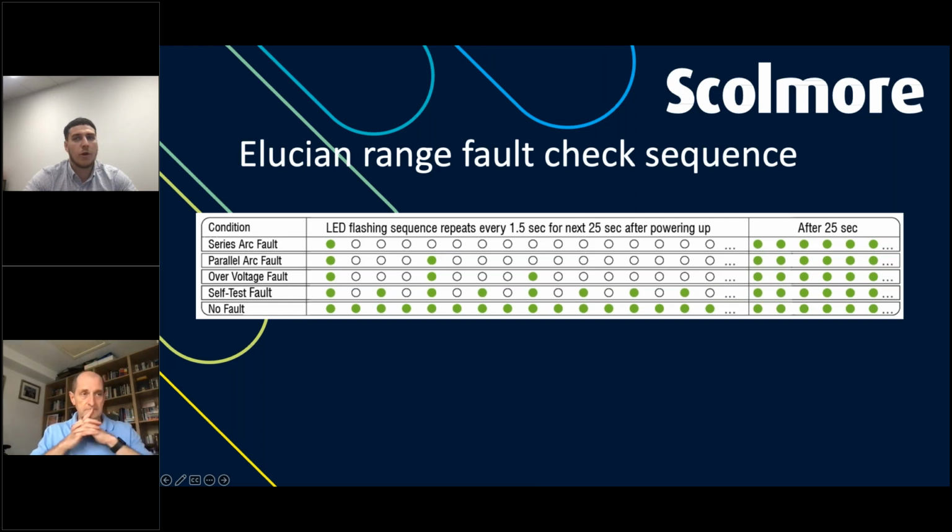Now, we know that we're using SPDs now. There's been lots of questions around that, from many moons about SPDs. But today, looking at arc fault detection devices, over voltage fault, that's looking at something similar to an SPD. However, it doesn't actually deal with the issue that's at large. It just simply operates. So if it sees over 275 volts, it will operate itself.